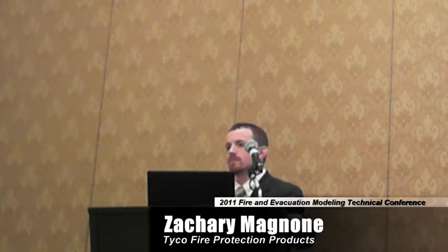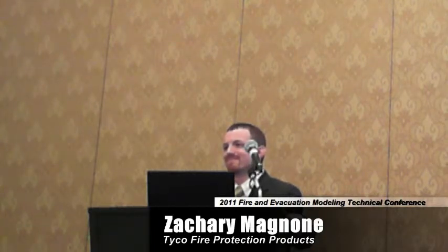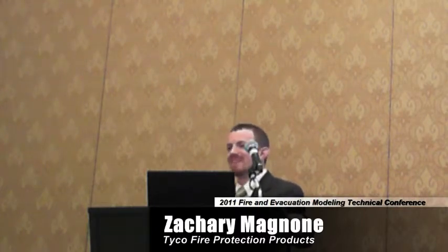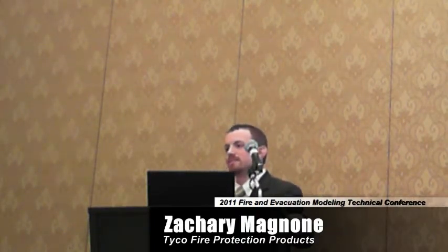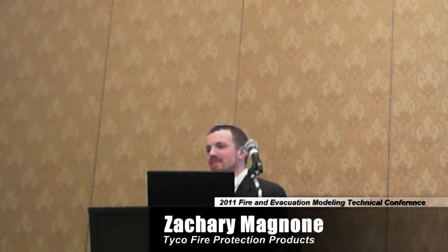Is there a one-page table which would relate what we have to plug into FDS, for a K factor of 5.6, 4.9, residential, 11.2 for storage, or if you're moving up to ESFR, or based on the design pressure? When I read this, I got so excited, it says practical method for designing, but for the day-to-day engineer, it's great, that's research. So what is it that we could use?